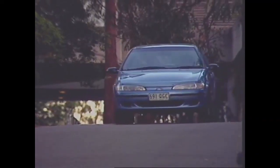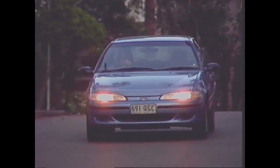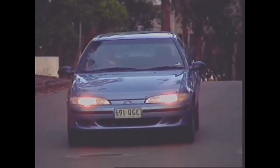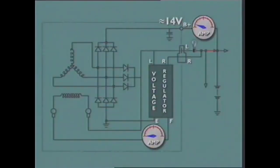As lights and other accessories are turned on and the load on the system increases, the current output to the circuits must be increased and the output voltage must be maintained. The regulator again adjusts the rotor field circuit, but this time increases the current flow and therefore the magnetic field strength. The induced voltage in the stator rises to maintain system voltage and increase current output.